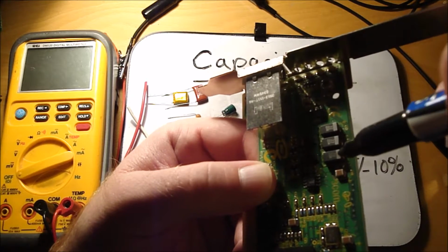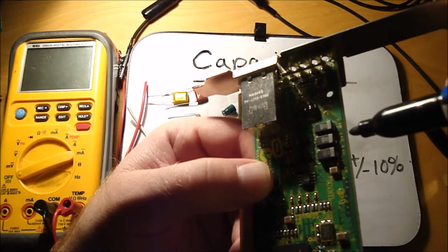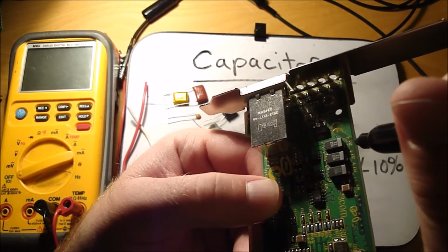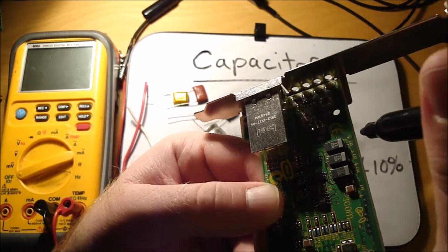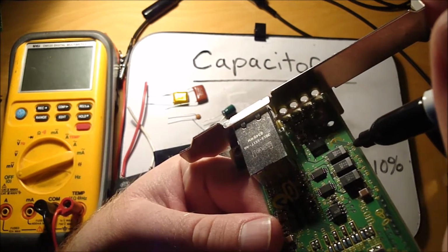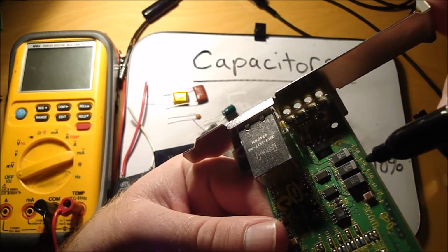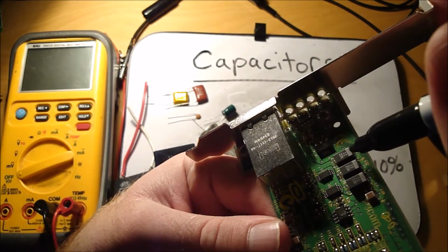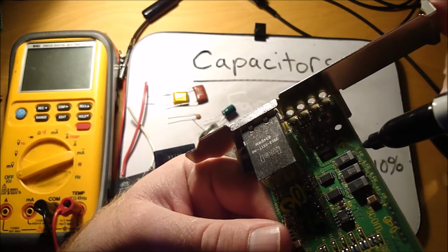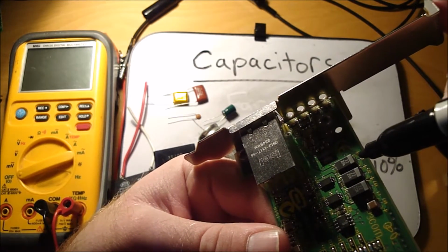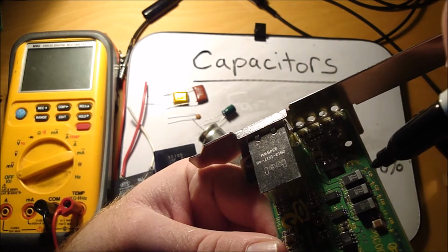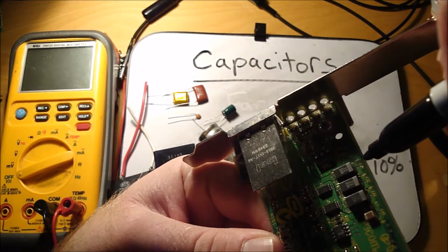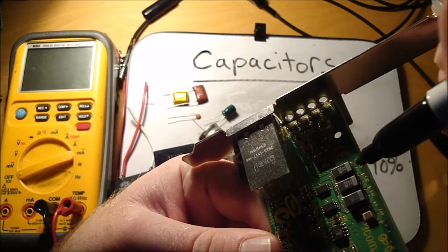So here you have some capacitors that are actually black. This is typically what a diode would look like, but these are actually capacitors. And the way I know they are capacitors is because of the identifier that they have on the board. So this one says C45, and a capacitor will always start with a C for the identifier on the board. So this is C45, C32, C44. So these 3 right here are capacitors, and the marking here on this surface mount capacitor is for the plus side, the positive side, and right there you can see a plus sign. So I know for sure that this marking is the plus side, and because it says C in front of the identifier, it's a capacitor.